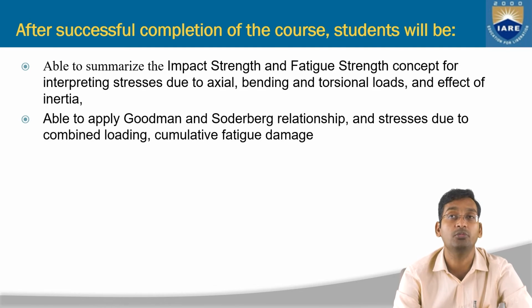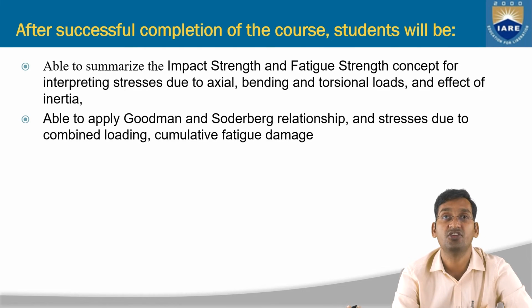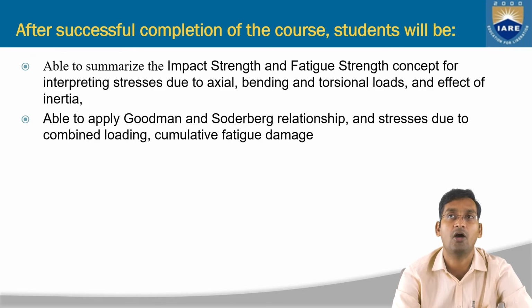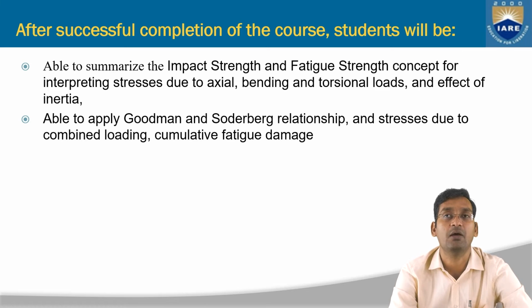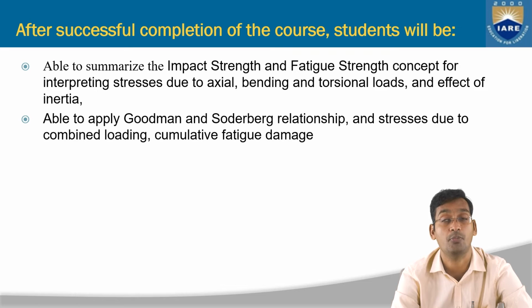Then by applying the Goodman and Soderberg relations, or which part can be used. Alright, the stresses due to combined loading, as I also mentioned: if they all combine, like the bending moment, point load, UDL, and uniformly varying load, all the forces and stresses acting at the same time, they can analyze that. And then cumulative fatigue damage. So overall fatigue, after that, how much damage will be there and how to find it, they will be able to analyze.